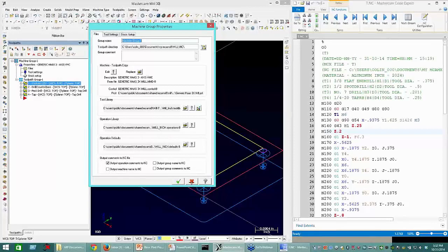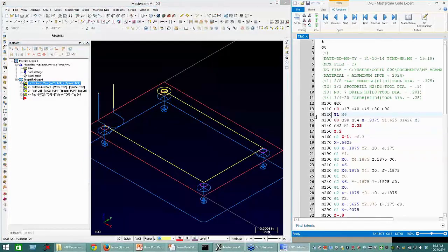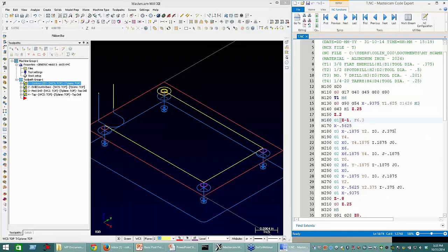So for example, let's say that normally you like having sequence numbers when you output your NC code. But you're running into an issue where you've got an older machine with a limited amount of memory in the control, so you need to reduce the size of your NC code. So every character and byte matters. If that's the case, we can do some things to reduce the size. Remove sequence numbers, and if we turn off sequence numbers, that actually will save a fair amount of memory. The other, we can remove spaces from our NC code. And finally, we could also set our arcs to use radius rather than IJK.